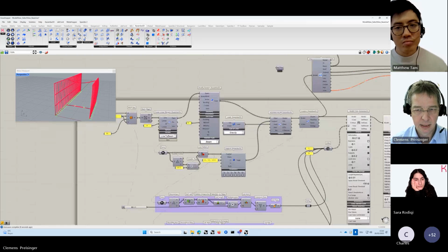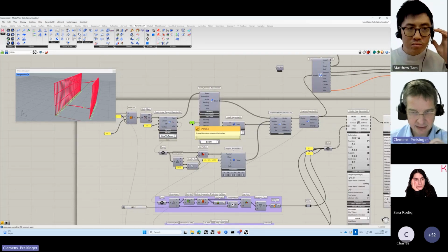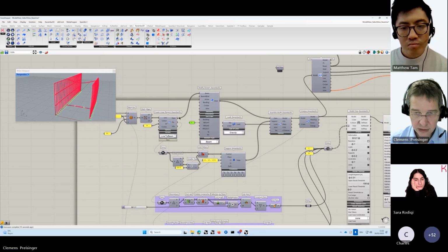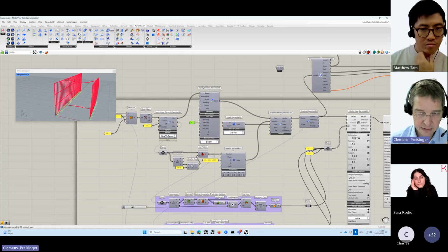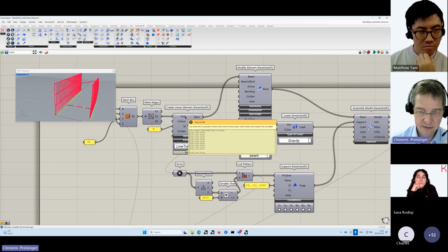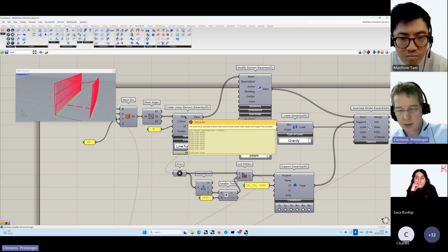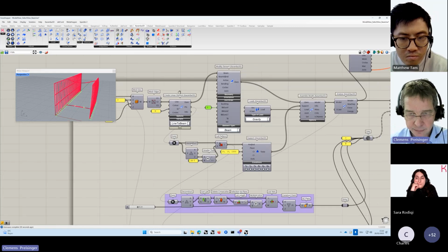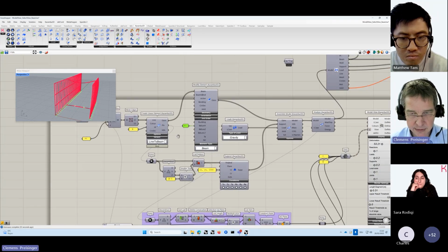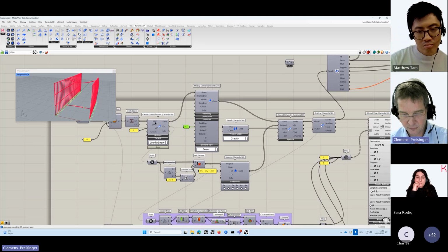And the assumption which Karamba does take is, first of all, if you supply here at the element creation component a polyline, then the buckling length is set to the distance between the starting point and the end point of the polyline for all segments. And this is one thing which is used.